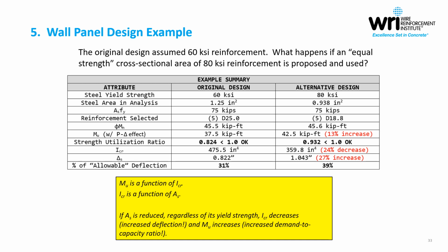So generally speaking, if high yield strength reinforcement is to be used, the simplest solution is to implement the 80 KSI steel area from the start. This will help avoid potential difficulty associated with validating an equivalent downstream conversion. So 80 KSI steel is certainly a viable alternative or initial solution, and doing this VE approach is not prohibited.